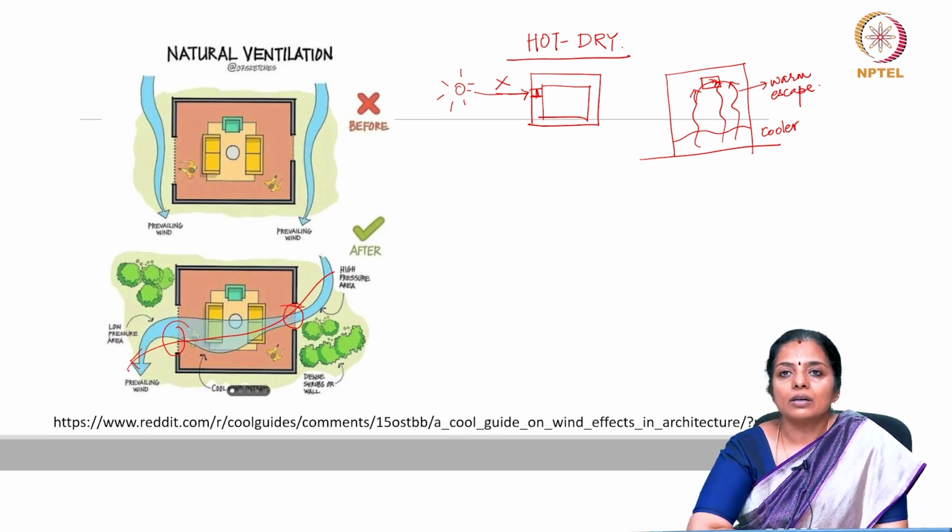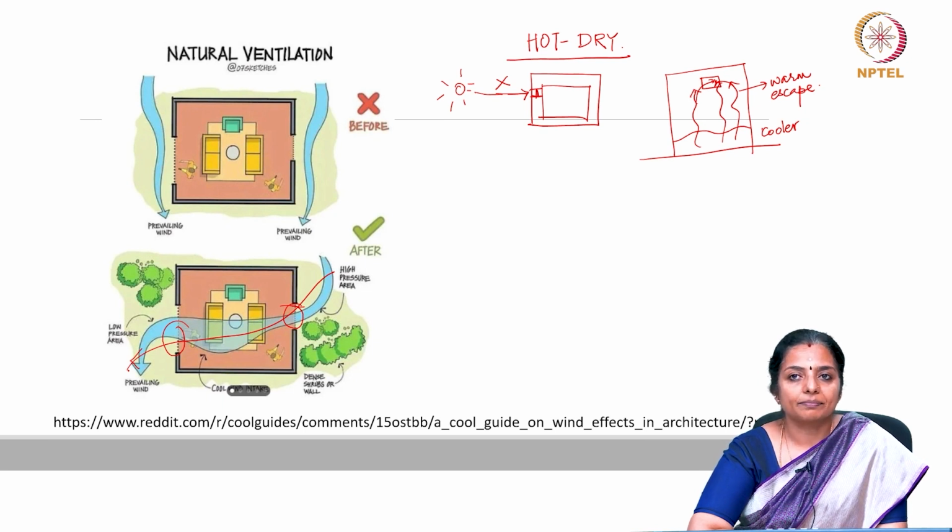Low windows allow ground reflected light. Light being reflected from the ceiling provides the most uniform illumination. The middle located window in comparison distributes neither skylight nor ground reflected light well. Some basic thumb rules can be followed in the positioning of the windows to enhance air movement.